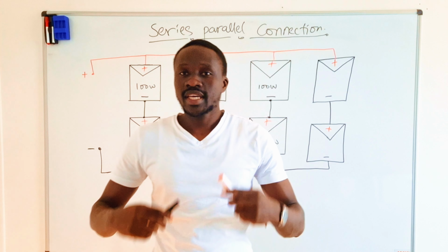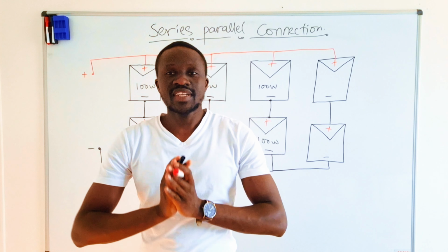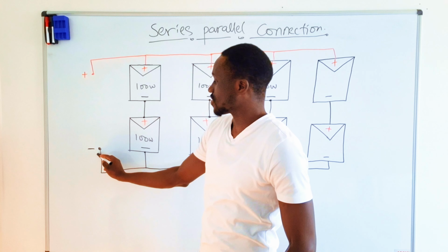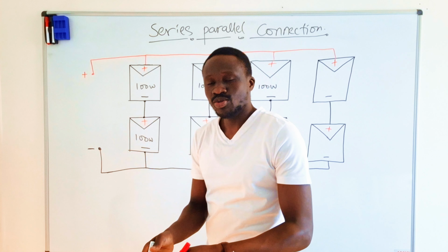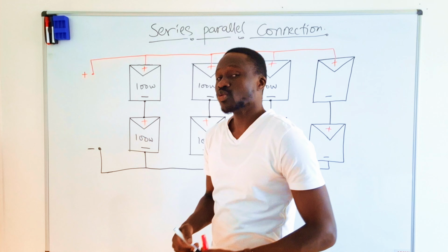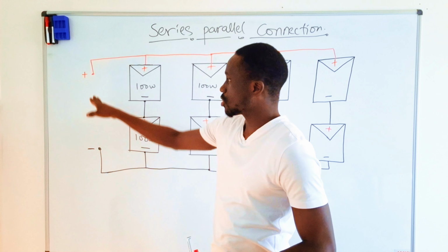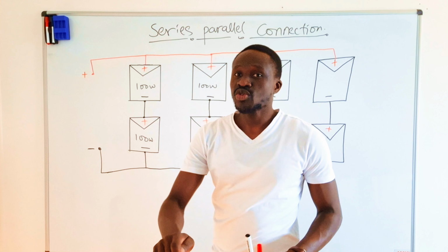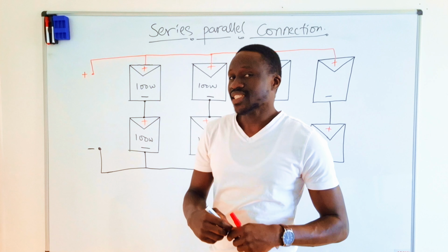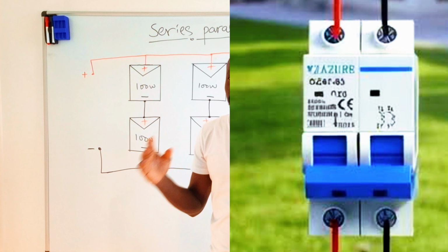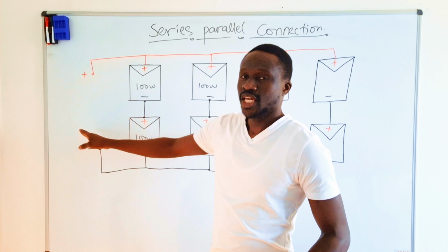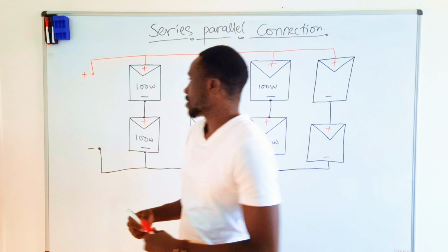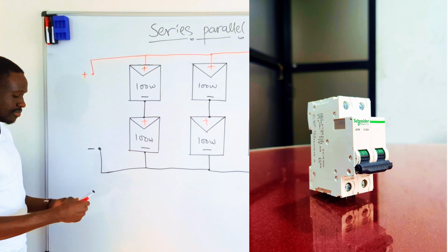We are going to go into the regulators. After connecting your solar panels, where should you connect these two terminals, a negative terminal and a positive terminal? The first thing to do, you need a control, because once you install the things, you need to first put a control before you connect a regulator. Which control is the circuit breaker. Always put a circuit breaker here before the cables go to the regulator. Okay? Let us try to put a circuit breaker.